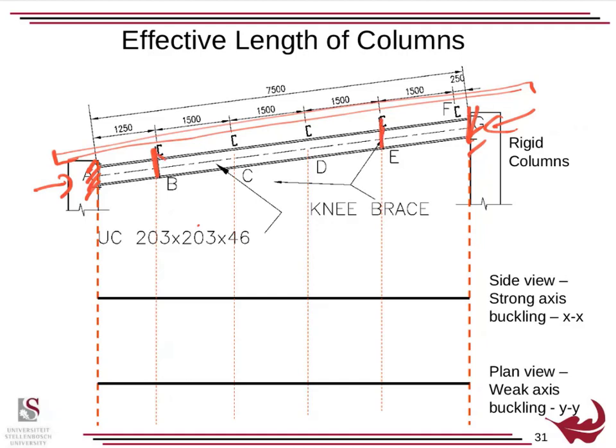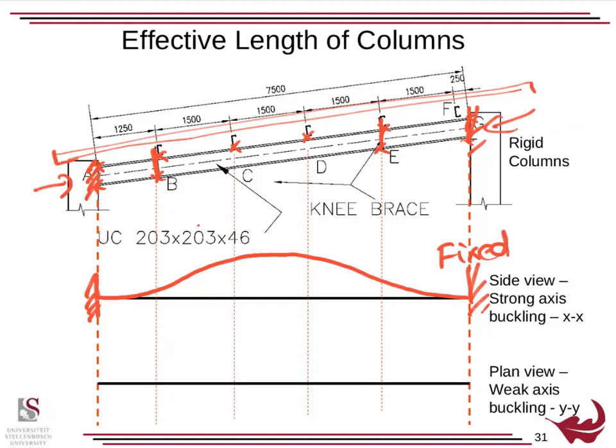So I've got various positions at which this section cannot move sideways. But in terms of moving up and down, this sheeting and these purlins will move with the structure. So here it'll be fixed, here it'll be fixed. Everywhere else it'll just be fixed and fixed, and an Lx of the full area.